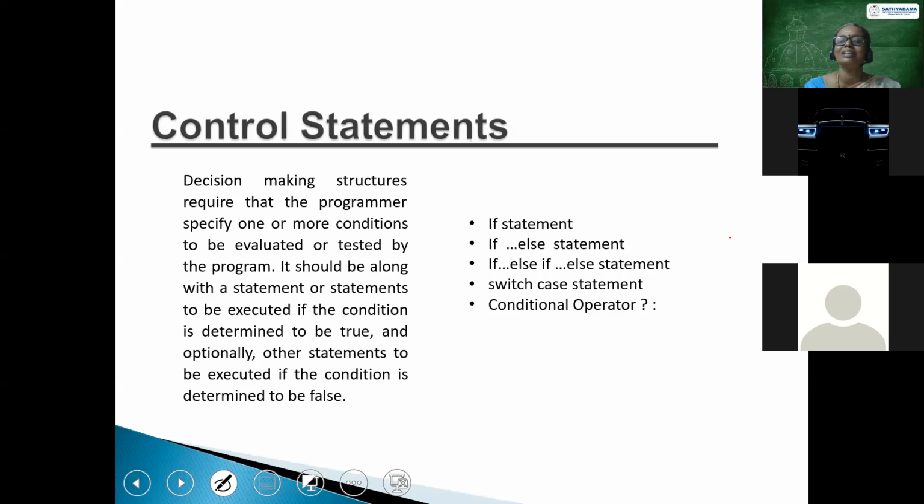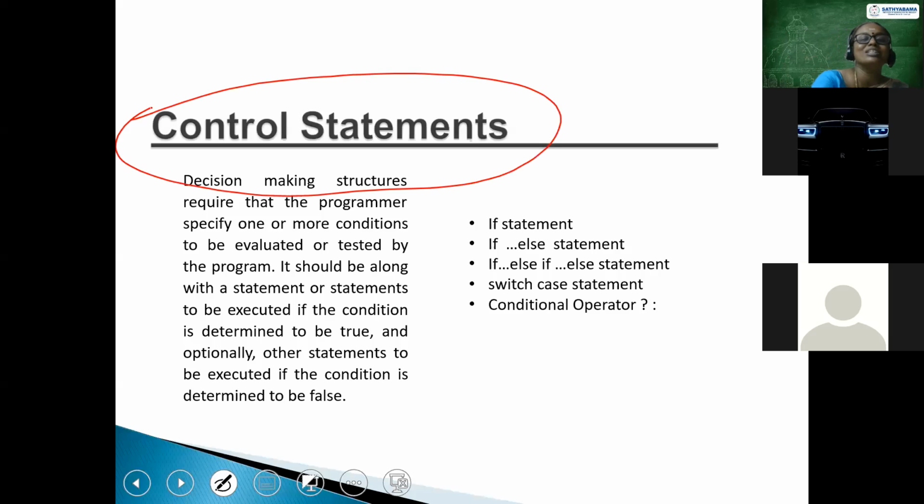All the motions will be captured by the sensors. But we have to write the conditions accordingly. For example, if smoke comes from a gas sensor and I have identified it, automatically I have to give a buzzer alert, or else my LED should turn off. For all this, the control statements are very mandatory.